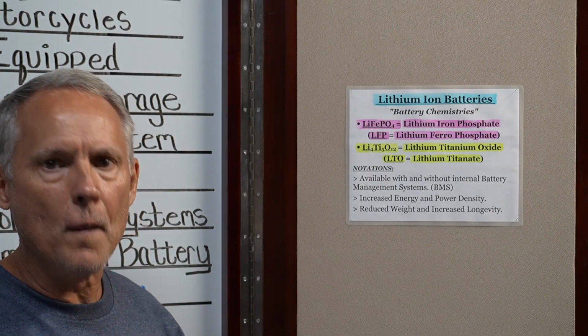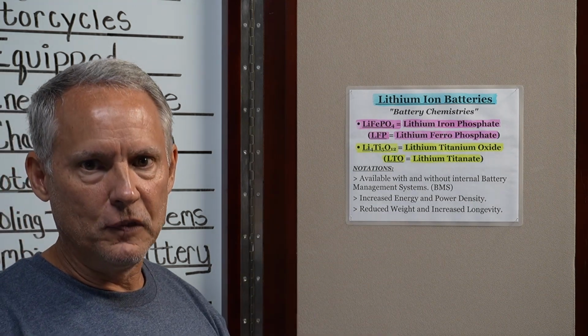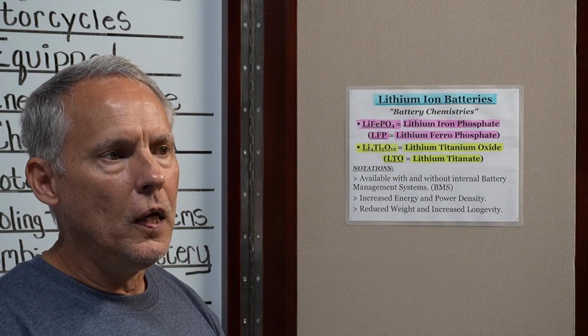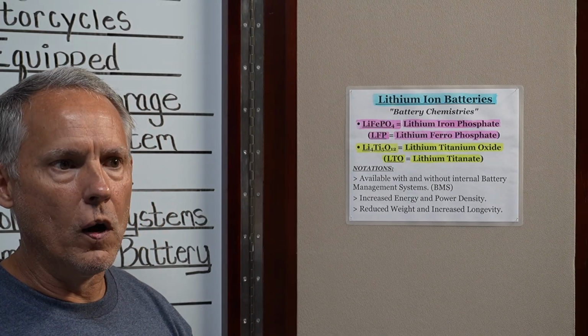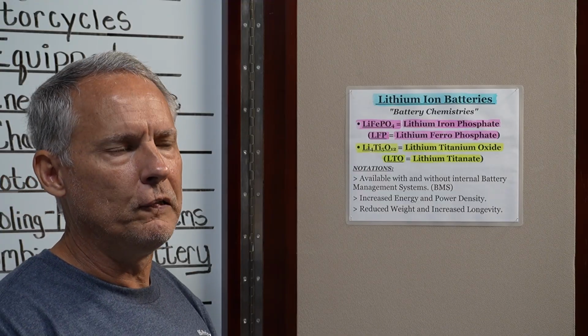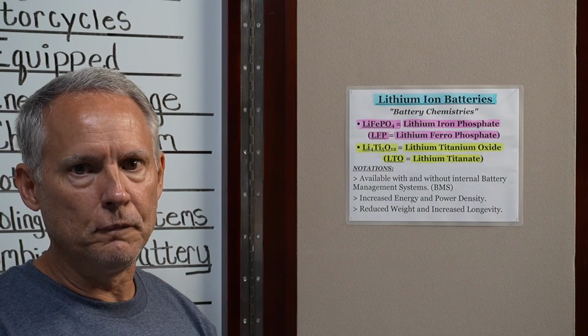You are on top of it, right? You may be able to get away with not having a battery management system. On the other hand, if you're going to drop a battery into your car and you take out a lead acid battery or an AGM battery and you want to put in a lithium battery designed as a drop-in replacement, do yourself a big favor and make sure it has a battery management system.